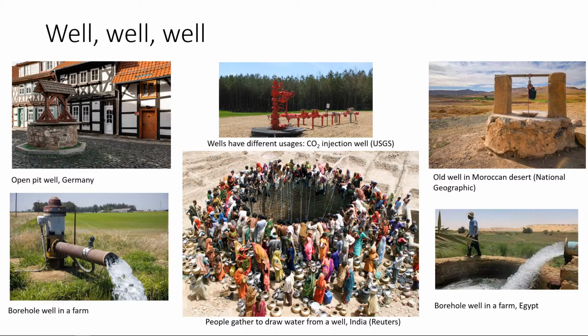Another thing is that you can put injection and pumping wells to create a hydraulic barrier, instead of the saltwater intrusion coming to where you are pumping. Basically, you put a hydraulic barrier before where you are pumping, so that it acts as a wall, and this wall will prevent saline water from intruding. That's one other use.